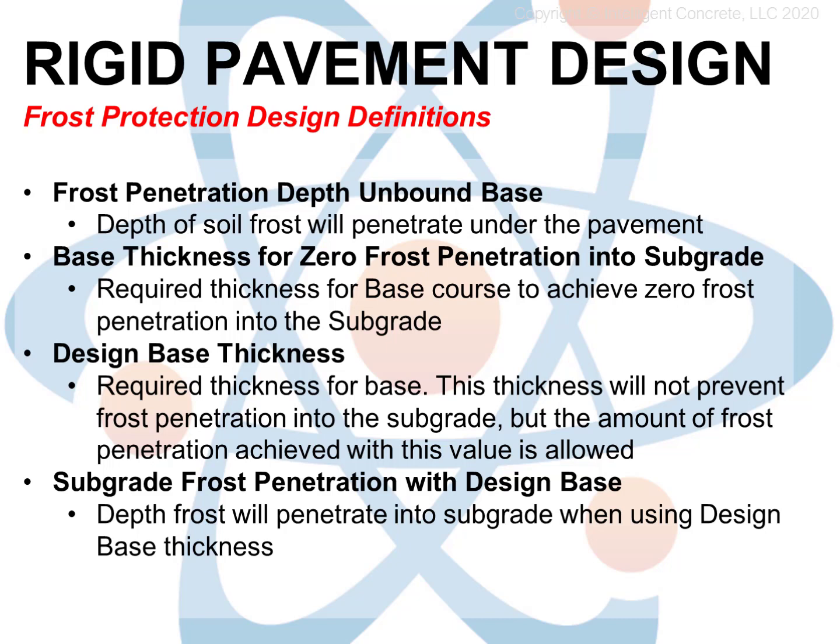Pavements can tolerate minor amounts of frost heave, and one goal of base preparation is to reduce the potential voids to a low enough point that what voids are left hold little enough water to make freezing and the ensuing frost heave manageable. Design base thickness is what it sounds like. It's how deep we have to prepare the soil layers, both base and subbase, under the pavement to keep frost penetration into the native soil to an acceptable level.